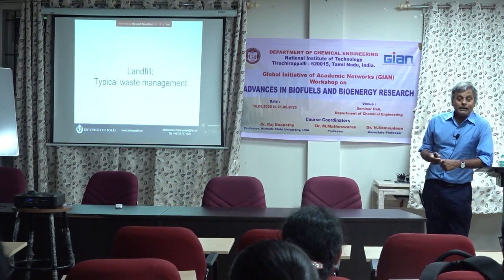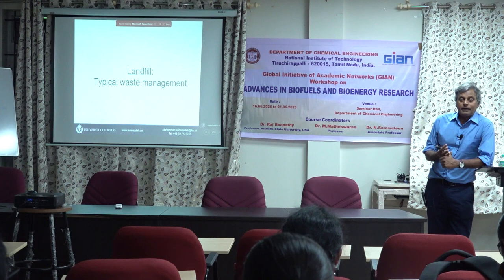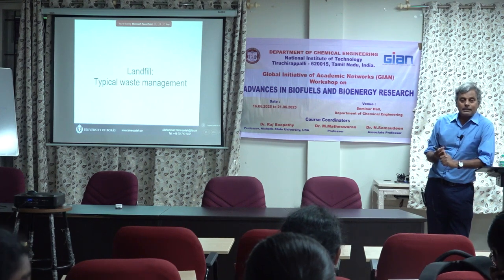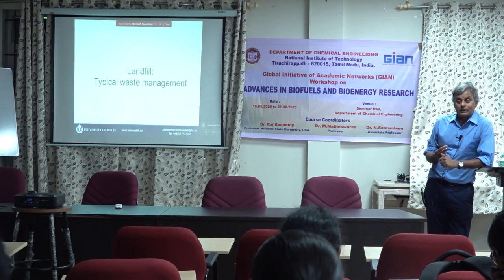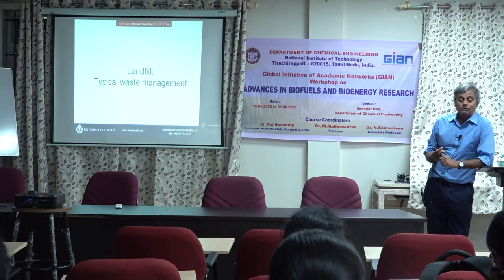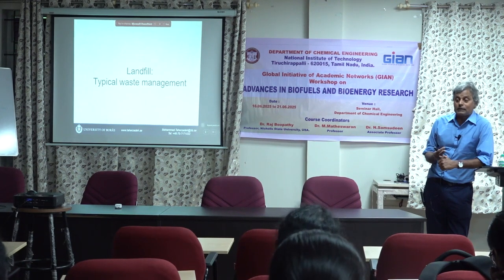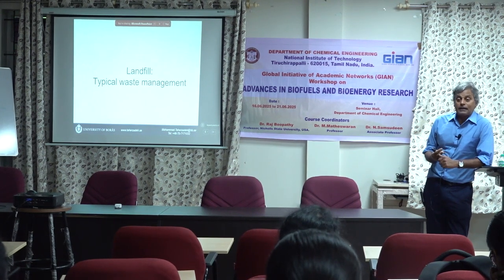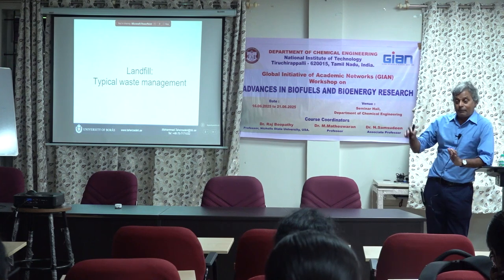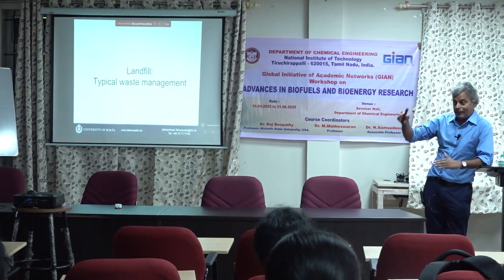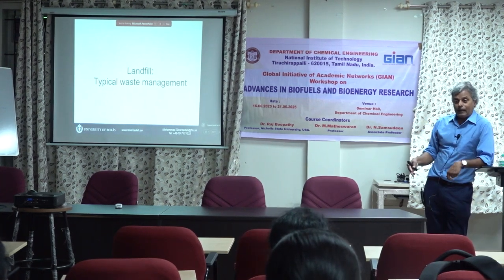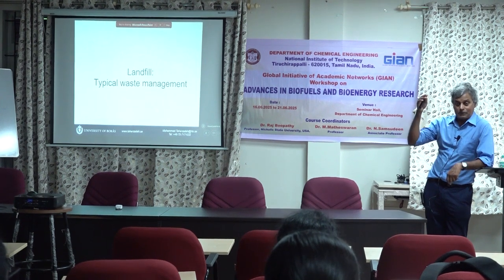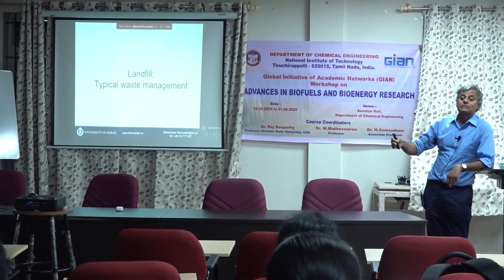So a landfill is like a solid anaerobic digestion process. Okay, so what they do in the Western countries is they call it a sanitary landfill. They compact the waste every day so they don't pile it up. And after 5 years of the landfill being in service, they put in a gas collection system.